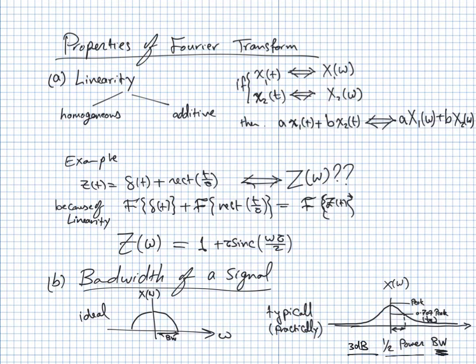There's another one that looks at 0.9 something. There are many definitions, okay? For the sinc function, particularly, we typically take only the main loop. And then we ignore all the side loops, the smaller oscillations. So for the sinc function, special case, we only consider the bandwidth to be the main loop bandwidth, okay? This is going to be my bandwidth, okay?